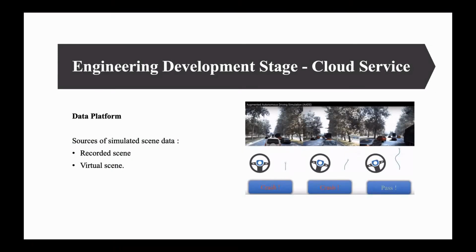The data platform stores all kinds of data from the unmanned vehicle in real time, including perception, vehicle status, driving track, software module status, and key log files detected, and makes offline statistical analysis, positioning of problems, and training models for the cloud platform. Driverless data could come from simulated scenarios or road tests.